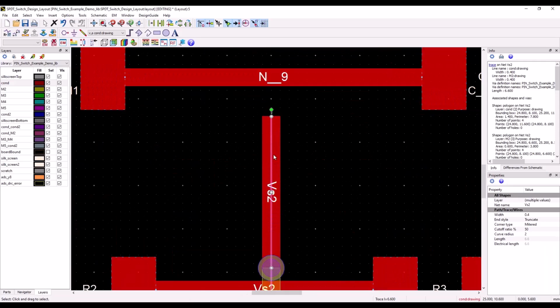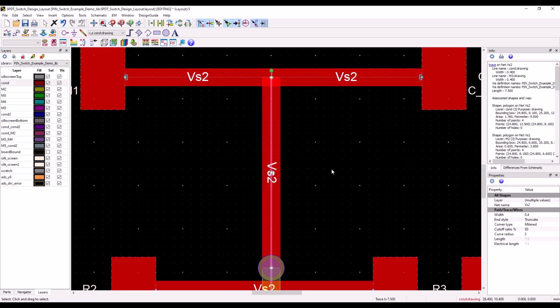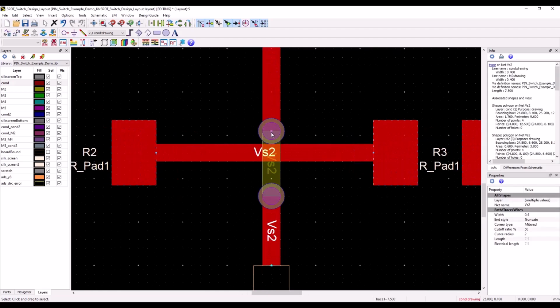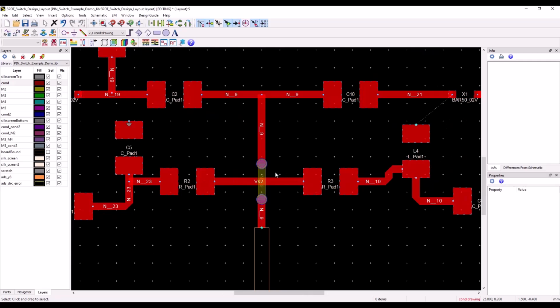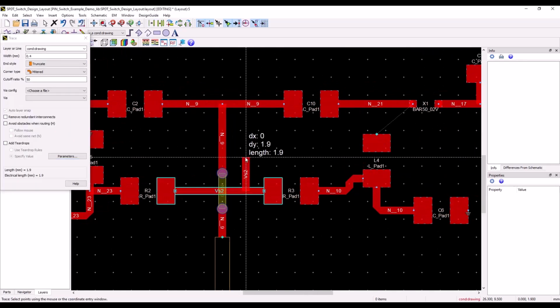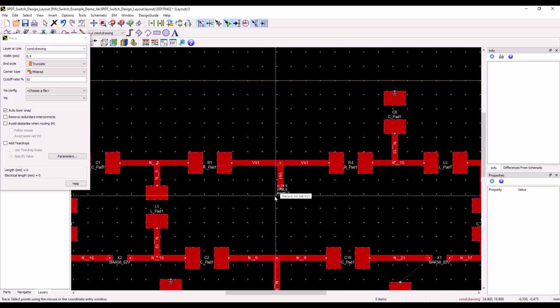And again, we can select the trace, press M to move at the desired location, then pick one of the vertex points to make connection to the desired point, which is basically in this case the antenna input getting divided in two sections. And again, by selecting the trace and the vertex points, you should be able to manipulate how much separation you need in layer number 2 so that you don't end up shorting your trace with the top layer.